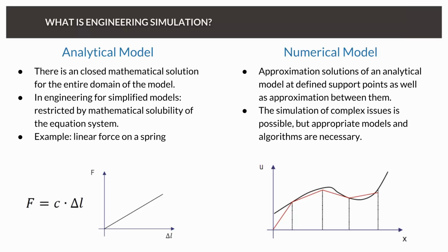The best way to understand what engineering simulation actually is, is to compare it with analytical models. We all know analytical models from school, and they are characterized by the fact that there is a closed mathematical solution for the entire domain of the model, for the boundaries as well as for every continuous point inside this continuous domain. Usually we use them in engineering only for very simplified applications, and they are usually also restricted by the mathematical solubility of the equation system.